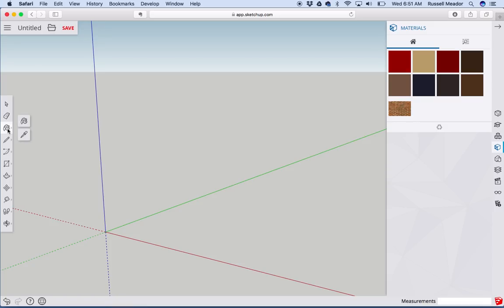We're not going to go right there right now. I want to spend a little bit of time getting you into some modeling. So when I click the little pencil here, the fourth tool down, I see kind of a traditional pencil and a squiggly line. The traditional pencil, I'm going to show you both really quick, and then we're going to come back to the pencil, is what I'm going to use to draw just straight lines. That pencil equals straight lines.